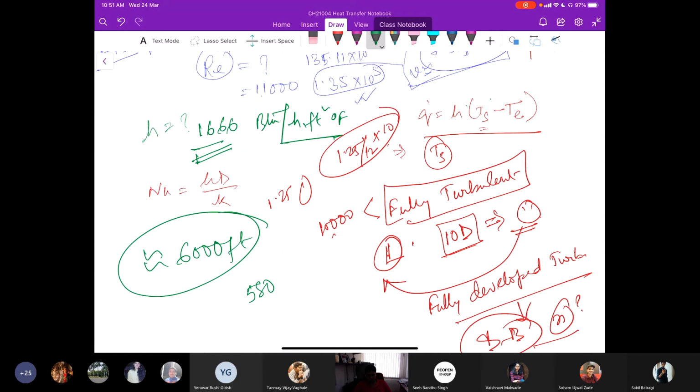Salman, leave your speaker on. I just wanted to hear. What is the unit of m dot? Sir, unit of m dot is pound mass per second. And you are mentioning BTU per hour. Did you get the point? When we multiply m dot with Cp, the pound mass gets cancelled because there is one pound mass in the denominator of Cp. The value that you are reporting is BTU per second.